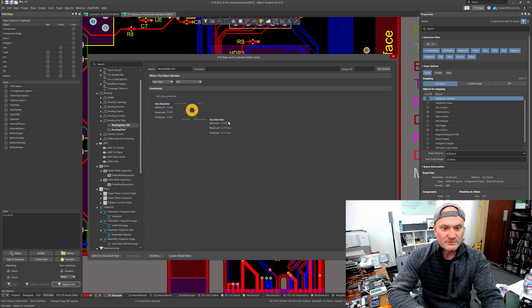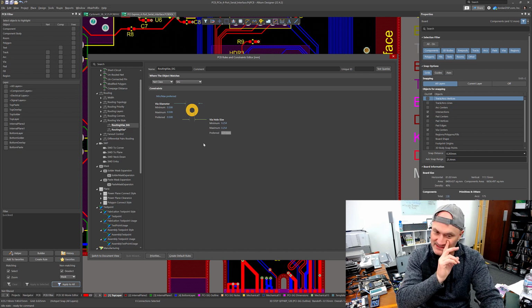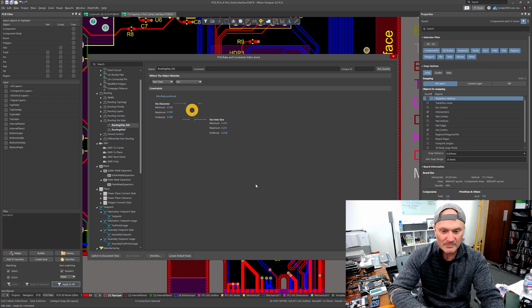Right. Now by doing this, we're going to come up with another interesting scenario: there are existing vias on this net right now that probably won't agree with this rule, so they will now be in violation, and if that's true, we'll see that happen. So I've created my via rule.